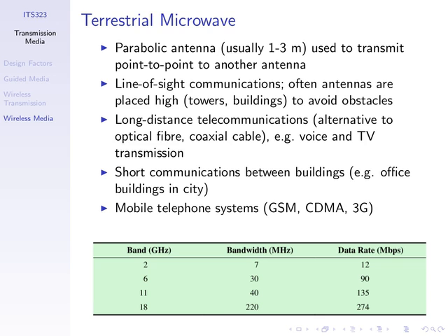So these terrestrial microwave links are used in long distance communications, as an alternative to using optical fibre. If it's too expensive or inconvenient to lay cables under the ground, then we could put some antennas on top of towers and have wireless links over tens of kilometres, as opposed to, over that distance of 10 or 20 kilometres between our two campuses, laying a cable, which is very expensive because you need to get access to dig under the ground under many different property owners.